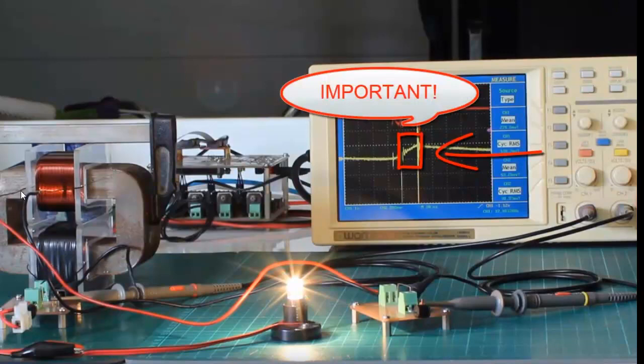That's a little bit like the LC circuit that we looked at just before. So it's a resonant effect. They're trying to push back on each other. The harder that this pushes back on this coil down here, the harder that this coil down here pushes back on this coil. But because we've found a resonant effect, that effect will happen very quickly between the two coils at minimum impedance. There'll be zero to even possibly negative impedance. So this is going to happen very, very fast, and that's why we had to zoom right in here to see the increase up here.